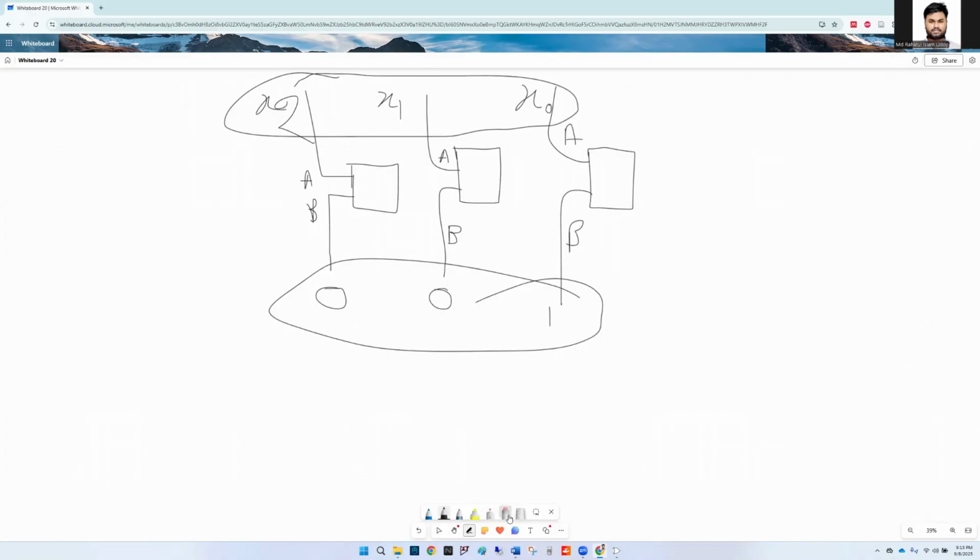But for making this an adder, it's simple, right? The circuit will be exactly the same, just the input will be different. Here you will have y2, y1, and y0, not a fixed 0, 0, 1. Instead of fixed 0, 0, 1, you will have variable input values, exactly the same as x2, x1, and x0.